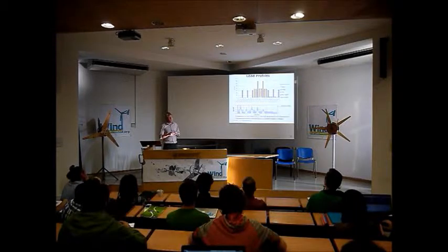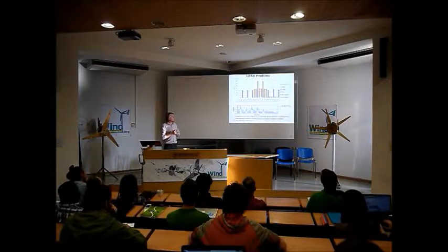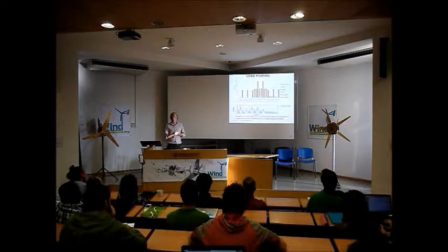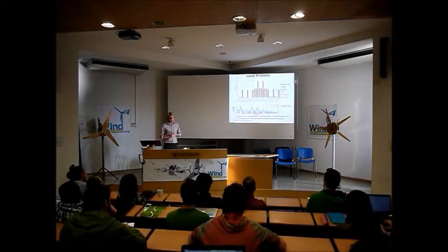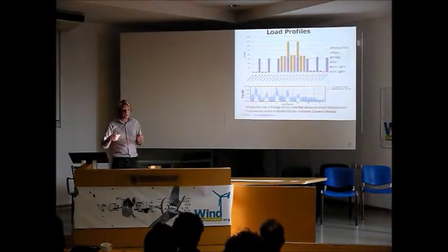It's important to think about what the off-grid system is going to be supplying, and you need accurate load profiles for what the energy is going to be used for. In Ethiopia, the most accurate load profile I could find was where we looked for productive uses of energy. This is different from education and communication, which is lights and phone charging. Productive use of energy is where you can use the energy to earn money. In Ethiopia, a standard business model is a barbershop. Everyone needs a haircut, and everyone will pay for a haircut.